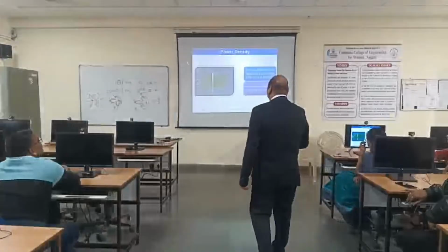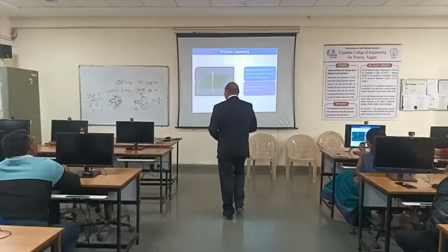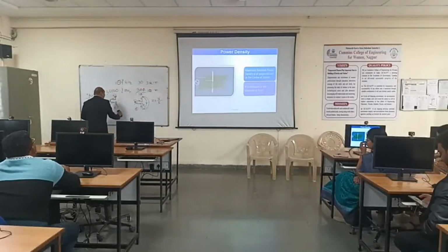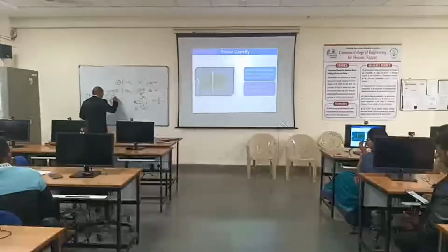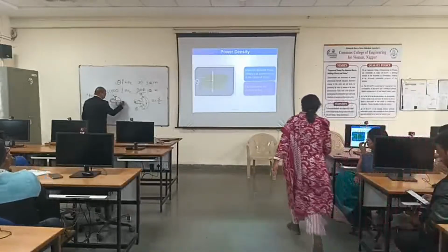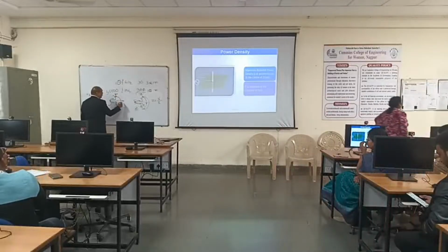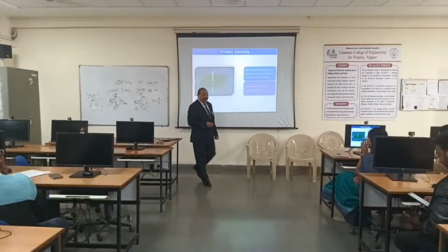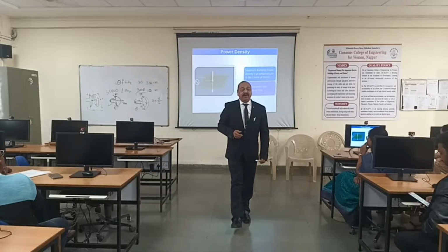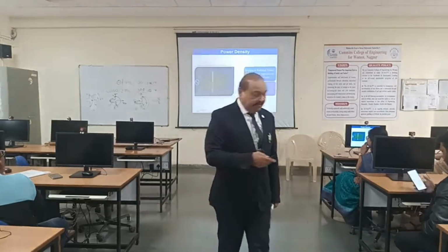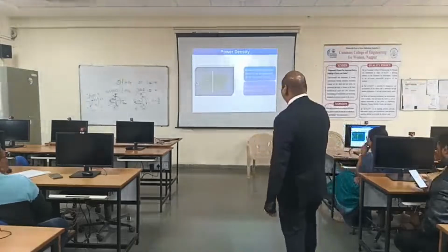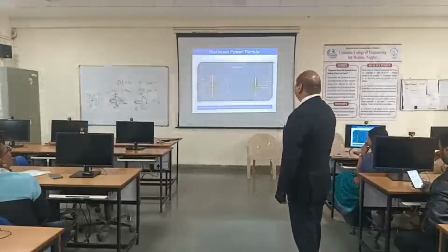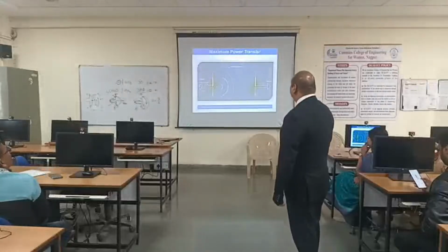Okay. Make it easy. So what I am saying, if this is an antenna, you will get maximum radiation. If you want to see radiation, then in the perpendicular direction you can get the maximum radiation and minimum along the antenna. So it can be maximum at the perpendicular and minimum towards zero here and max here. That is the way the power has to be distributed along the antenna if the antenna length is lambda by 2, half of the level. Means lambda by 4 upper, lambda by 4 lower. Next. See, these are the ways it radiates.